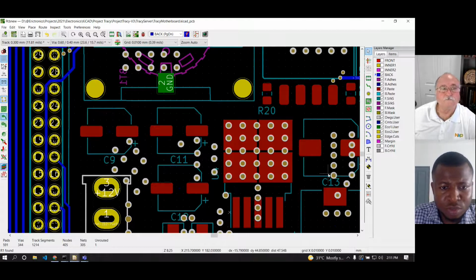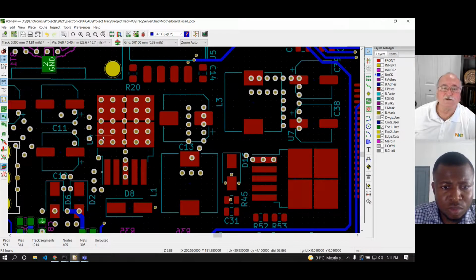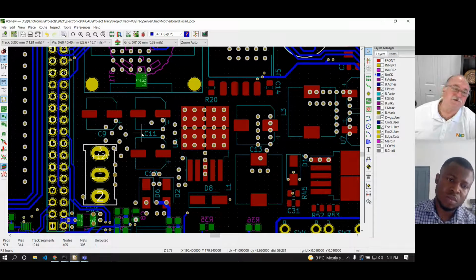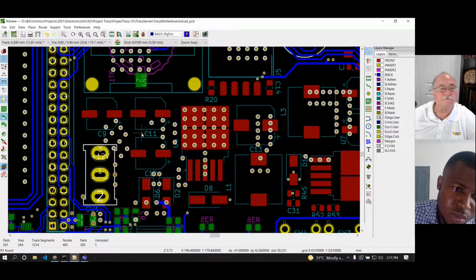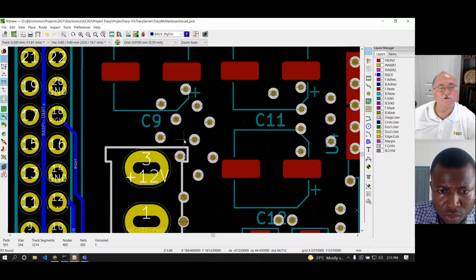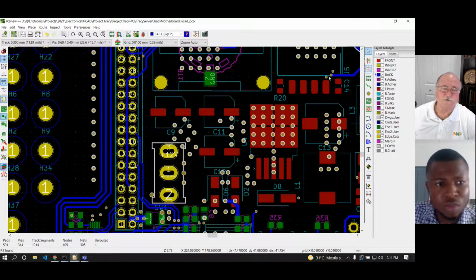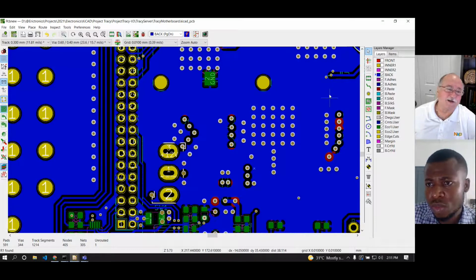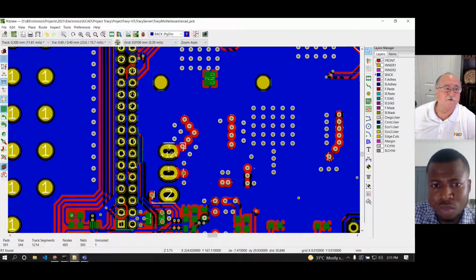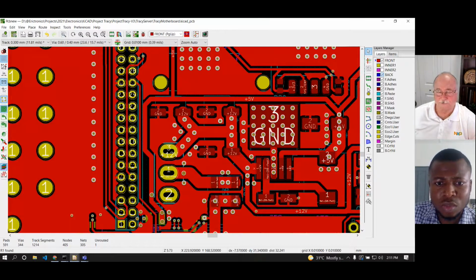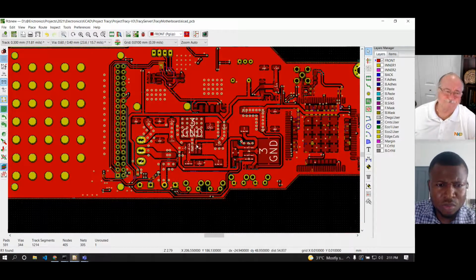And the voltage regulator takes the energy from the big capacitor and stores it in the one on the other side of the voltage regulator integration circuit, the inductor capacitor. And then that capacitor is the source of energy for the ICs. And then in the region of each IC, you have a large capacitor that is filled from the output capacitor from the voltage regulator.